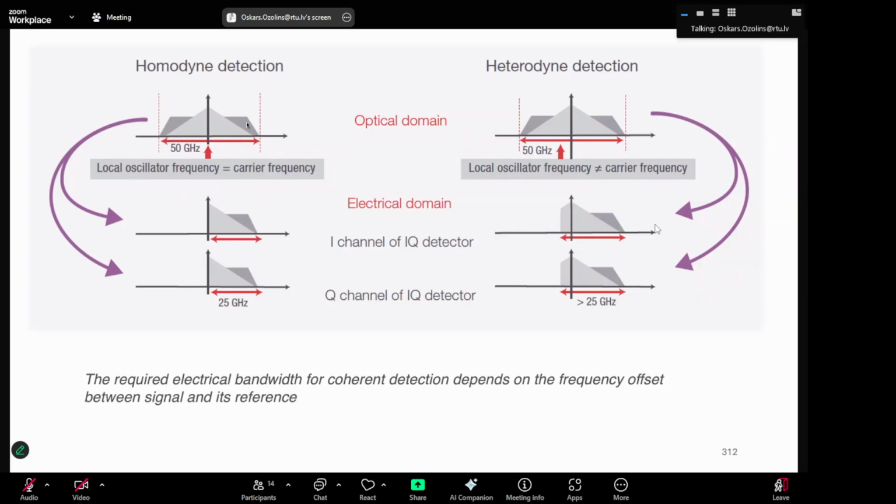So in self-homodyne detection, you probably use the same light for transmitter: you split the laser and use one in the transmitter, other in the receiver, but then you need to transmit the laser light on a separate fiber. So it was an interesting approach in multi-core fibers, when you can use one of the fibers to transmit the local oscillator, and on other cores you can transmit information.